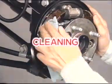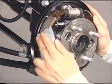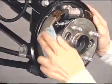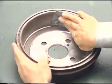After this, clean the brake lining. Be sure to wipe off any oil stains on the brake shoe lining using sandpaper. Also, clean the inside surface of the brake drum.